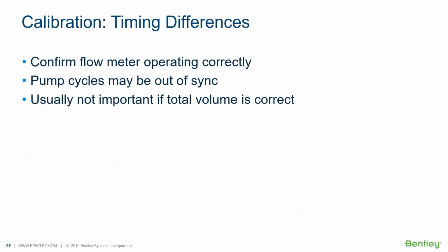What happens with pump flows is you get some shifts in peak. When the pump cycles, the pump is on in the real world and off in the model, it may make the model look bad, but the flows are different. If the peak flow and the off periods are about the same and the flows are about the same, you shouldn't get too worried about that, as long as you're getting the right total volume of flow down the line.